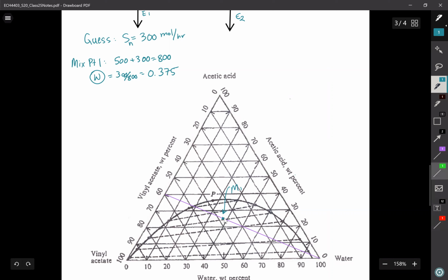And then I've got a tie line that's pretty close, but I'll sketch in just another one, just so you get the idea of, well, it's really close. We're just going to probably use that tie line actually. All right, use the tie line to find the intersections of the equilibrium raffinate and extract composition. So I'll pause again and let you practice.